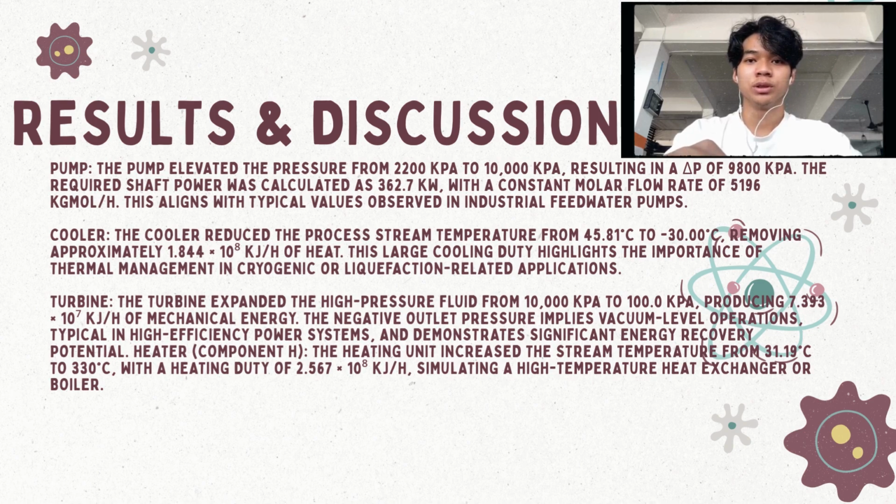The cooler reduced the process stream temperature from 45.81 Celsius to negative 30 Celsius, removing approximately 1844 kilojoule of heat. This large cooling duty highlights the importance of thermal management in cryogenic and liquefaction related applications.